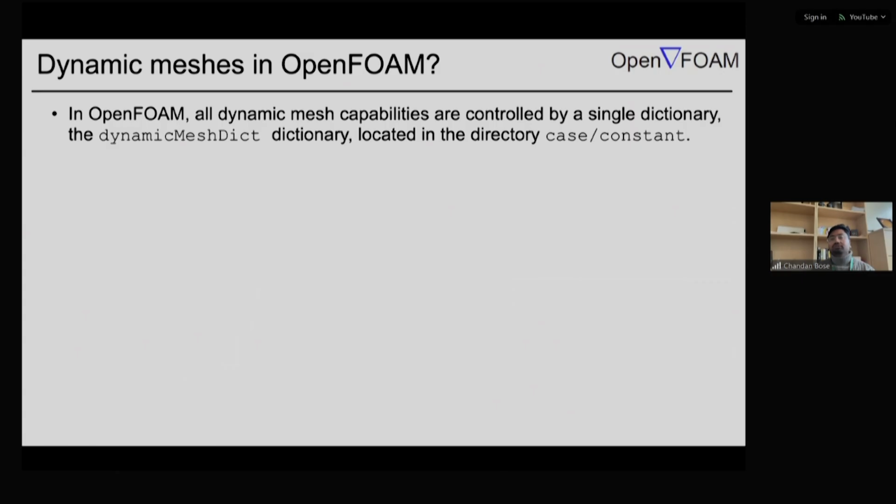All right. So the first thing is that these dynamic mesh motions are controlled by different code libraries that are already written within the OpenFOAM framework. So we don't have to code them separately, but we need to call those functions and then prescribe the motion, whatever we want to incorporate in terms of the motion of the body. And the file that we need to additionally include in this case is called the dynamicMeshDict.